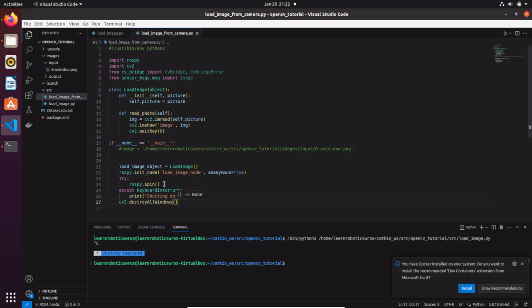Okay, so here we have started to initialize the ROS environment somehow. What we need to do now is to adapt the constructor here. First of all, we're gonna create a subscriber that will subscribe to the topic that contains the data of the image that we wanna display, and that the camera in Gazebo will publish.